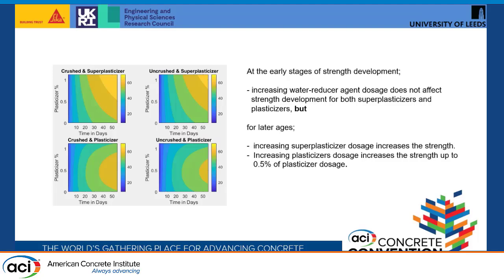Also, increasing plasticizer increases the compressive strength, but here we should talk about an optimal level. It's around 0.5. Beyond that level, no need to put in more plasticizer, because we can see it is an optimal level for plasticizer content.